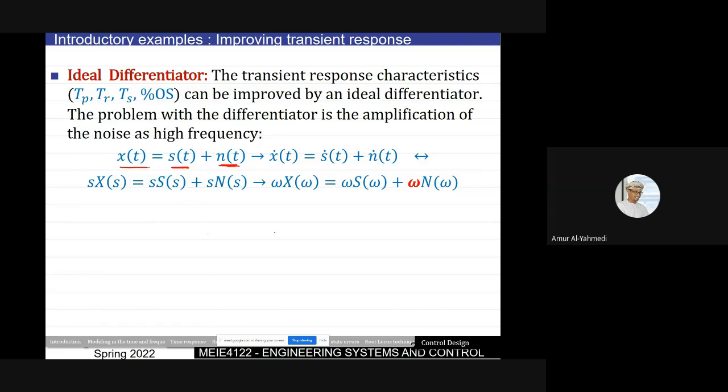The example I would like to give here: suppose I have a camera, okay, and I am determining, for example, the position of the robot, the xy position of the robot. If I try to differentiate to get the velocity, and I have an error, let's say my x is equal to 1 meter plus or minus 0.1. Suppose I have noise; the camera does not give me the position accurately, so I have plus or minus 0.1. When I try to get the velocity x dot of this one, what will it be? It will be the change in position, delta x over delta t.